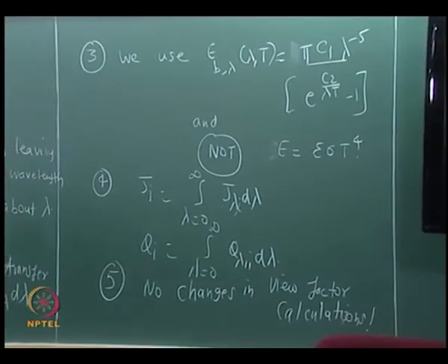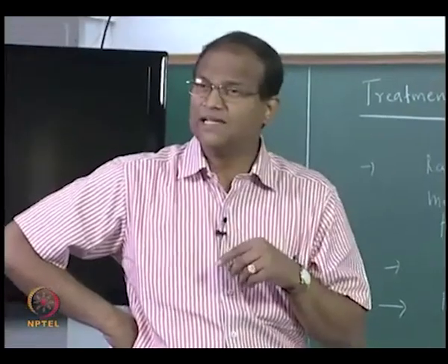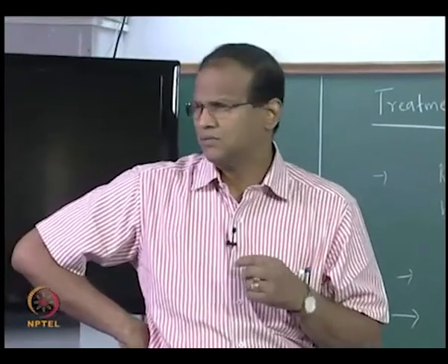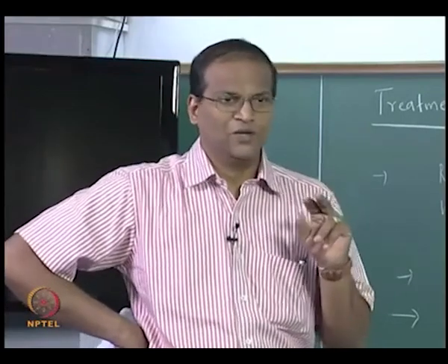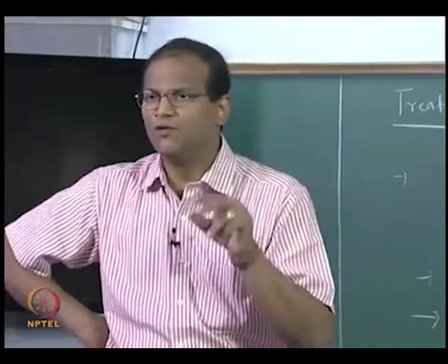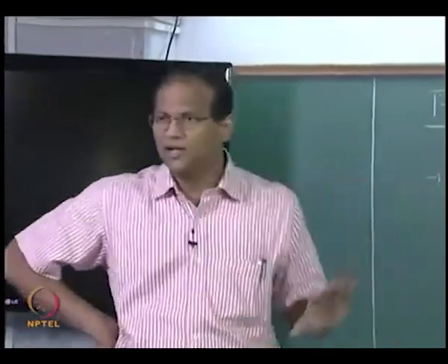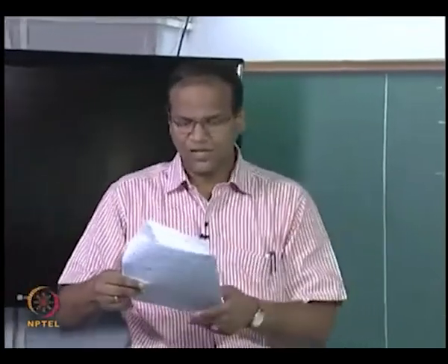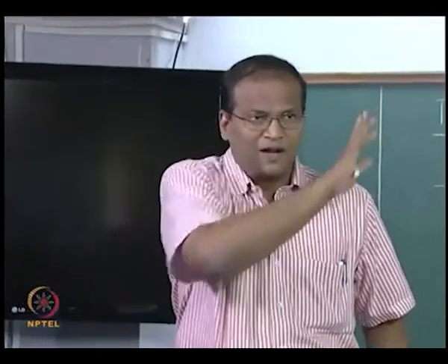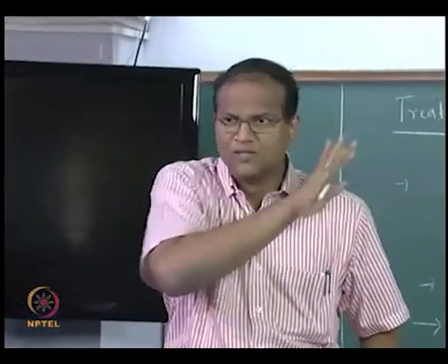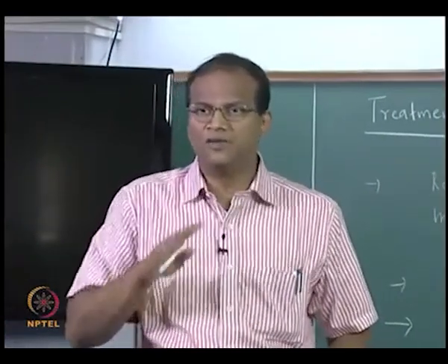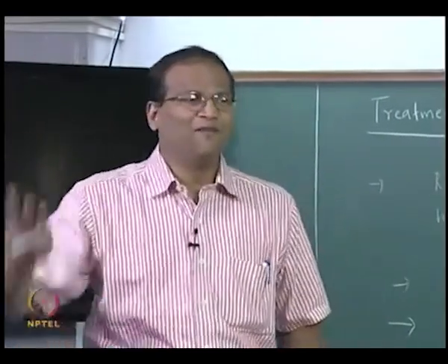So how do you get the reflectivity? It is spectrally dependent. Therefore you have to invoke Kirchhoff's law, and say that alpha lambda is equal to epsilon lambda. So this completes the formulation, this gives you the broad framework after going through these important rules. This is like prerequisites. Once we have all this, then we write the formulation.